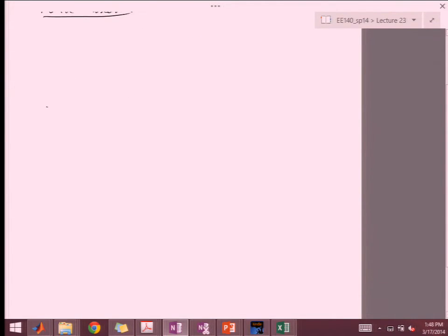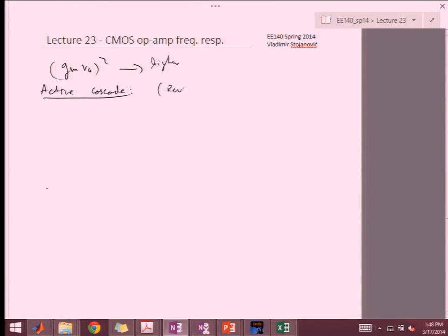So just for review, for everyone to catch up, what we're talking about is something like this. This is your V input. And then here, instead of just putting the bias voltage, you put an amplifier, and then you feed back. So this is your V bias. So what this does, if VI goes high, this goes low, this guy goes high.